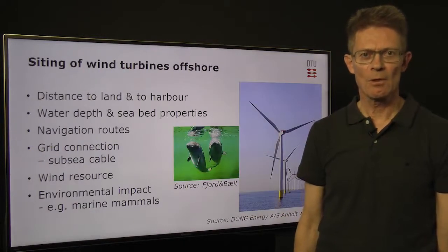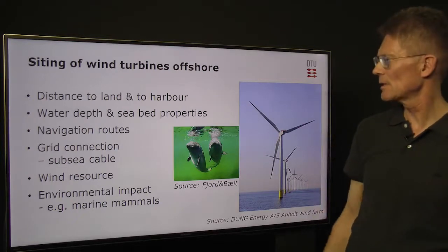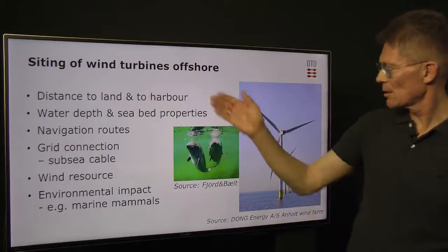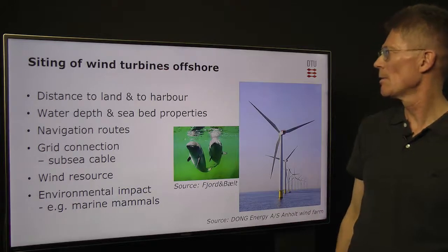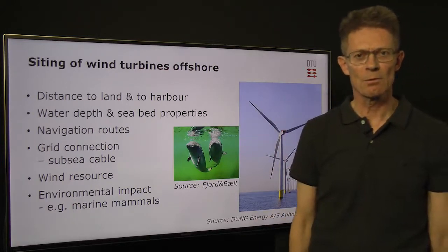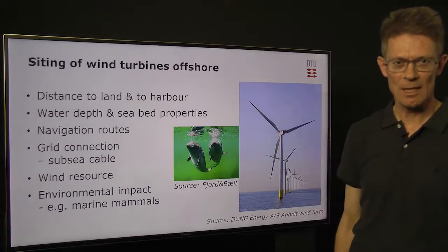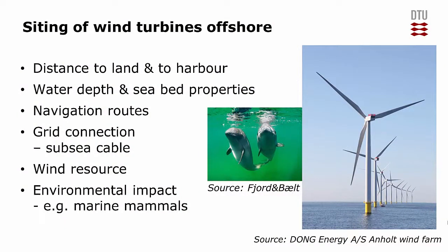When we move offshore, we do a similar exercise. The issues are slightly different. The distance to land and to harbor is very important because that will determine how far we have to transport our wind turbines in the construction phase, but also in the operation phase. The water depth and seabed properties are very important when we design the foundations of our offshore wind farm. The deeper the water, the more expensive the foundations.